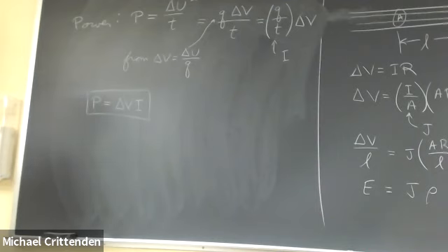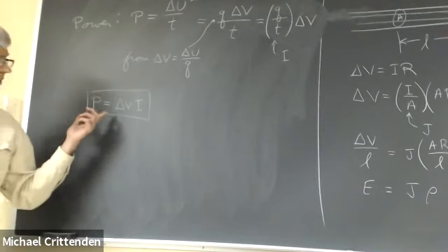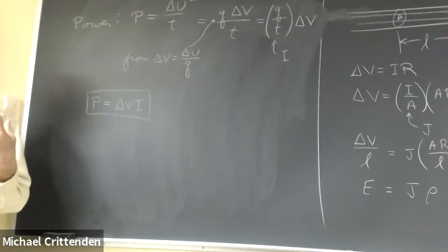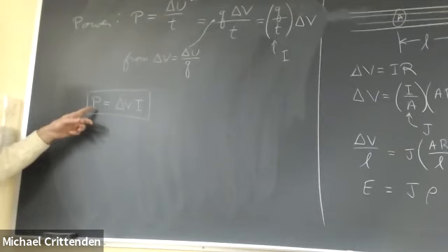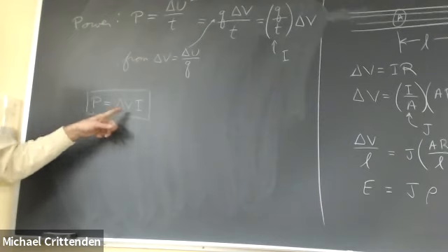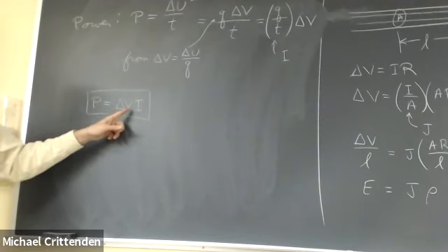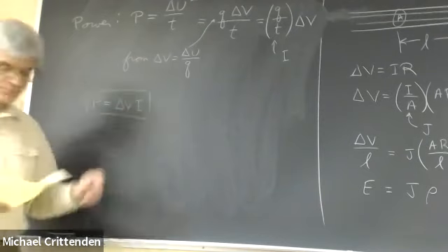So if you got a light bulb, and on top of the light bulb, it says 60 watts, 120 volts, as many of them do. You can stick those numbers into this, and that tells you that if you operate it at 120 volts, there'll be half an amp going through it. 60 watts divided by the 120 volts, half an amp.